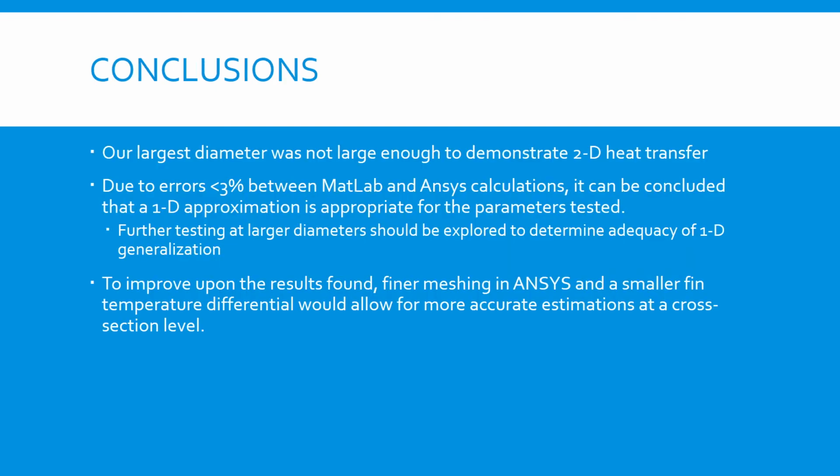The largest diameter tested was not large enough to demonstrate 2D heat transfer. The errors were less than 3% between the one-dimensional approximation run in MATLAB and the Ansys calculation, which means for these parameters a 1D approximation is appropriate.